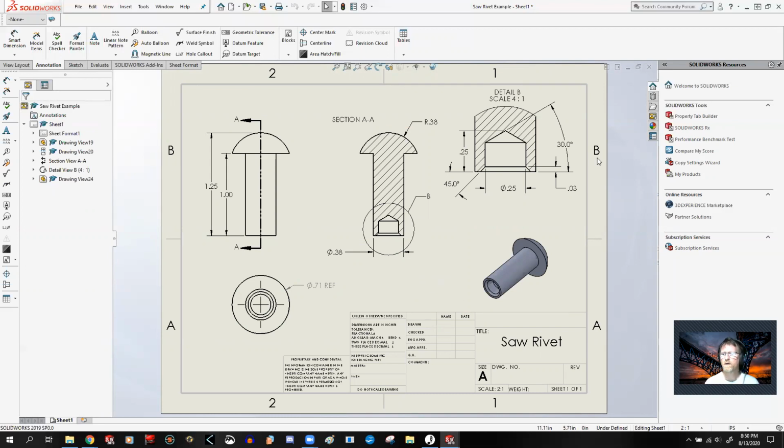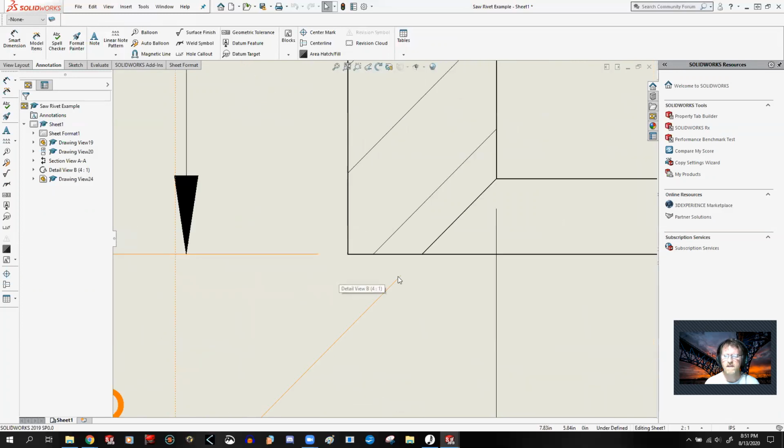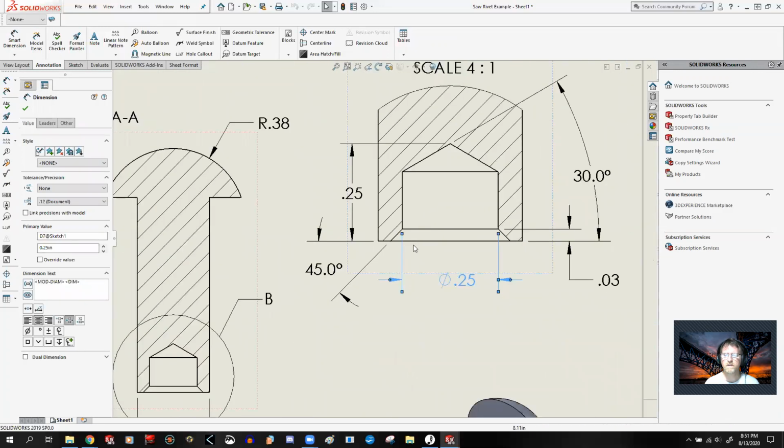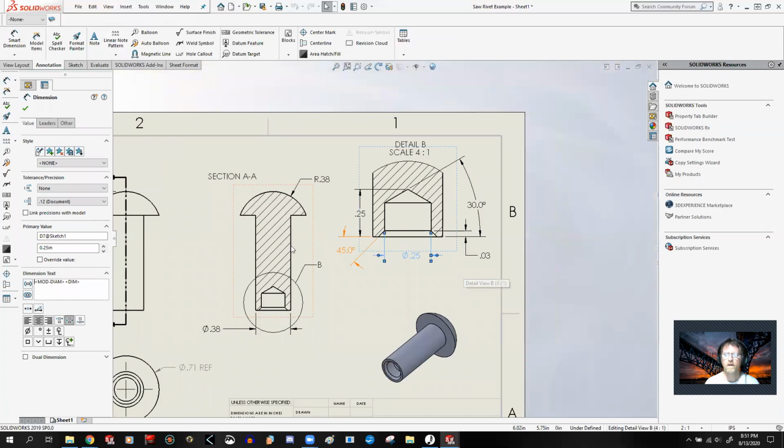So you'll notice I have all of these spaced out very nicely, so you can clearly see what everything's pointing at. The numbers are way off of the part itself, and the lines aren't crossing. Notice how these witness lines here are away from the points that they're looking at. They're close, but they're a certain distance away. Same thing here, same thing here. So these are witness lines. So that's a witness line right there. And if you want to move it, you just click on it, and then you grab that little control point and drag it up and down.